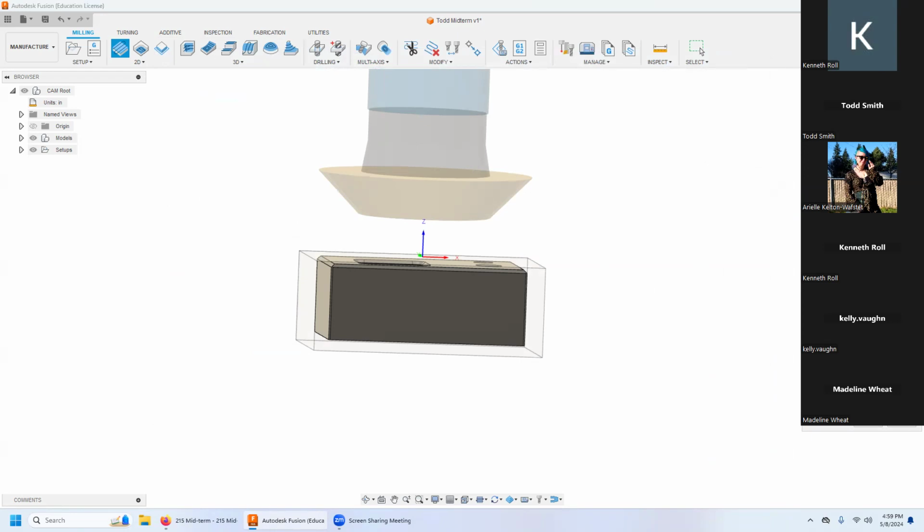Okay, our spindle speed is 7 thou, and you guys have all seen now how I got there. And we can go through that again if you guys want at some point. Cutting feed rate, we're going to go with 150 for roughing. Then we're going to slow it down for our finish. Plunge, we're going to go with half of our feed rate, or 20, whichever is lower, which happens to be 20. Okay, any questions on that?